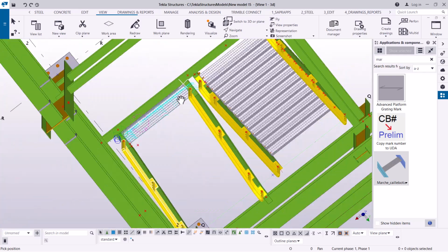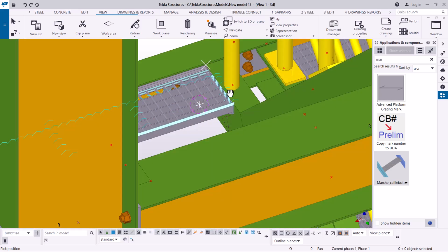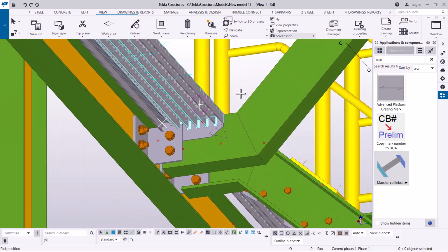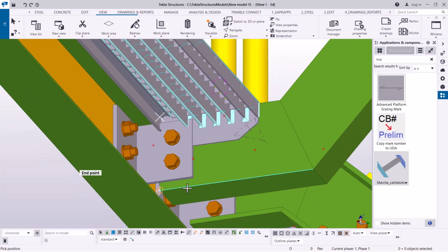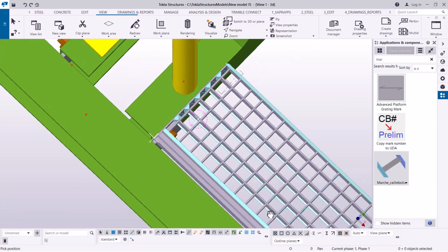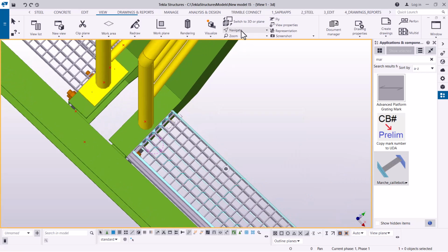You can see that. Perfect. If I come to navigate there, I'll be able to pick on it and turn it around like that, and you'll be able to see we have the thread. But don't worry about the clash here. We can decide either to reduce the cleat slightly and bring it down slightly to that level. Then the extended part that remains will be part of the assembly with the thread. So that should not be such a big worry. The key part is just how do you know how to fix this thread, which best tool to use, and how do you apply them.